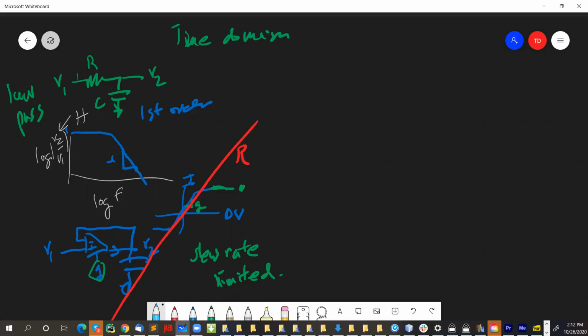So the dual circuit of this is called RC low pass. The dual of this is a CR, and that will be high pass. So let's imagine, how can you make a high pass filter out of this? High pass means it only passes high frequency and doesn't pass a steady state. Well, you can imagine how it is. You just swap the resistor and capacitor, right?